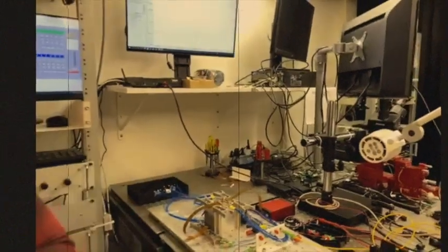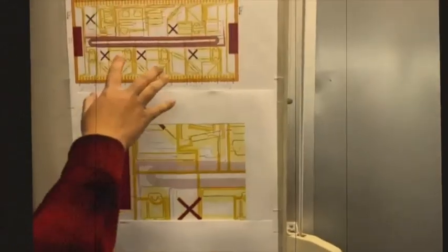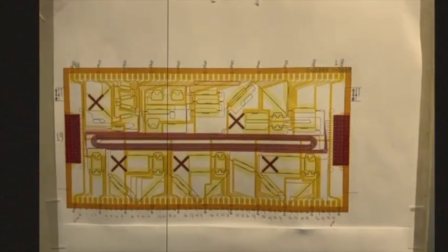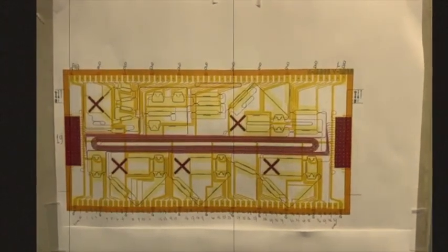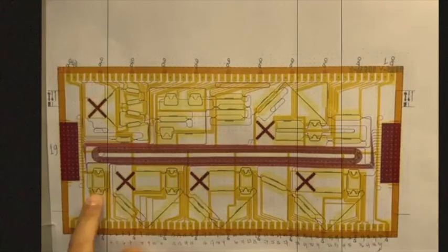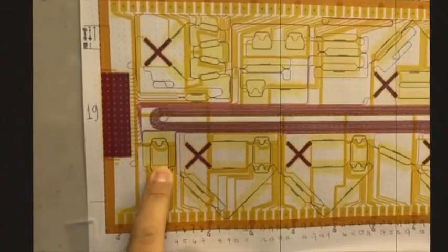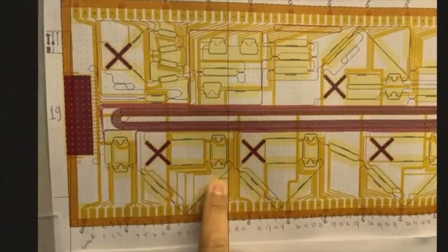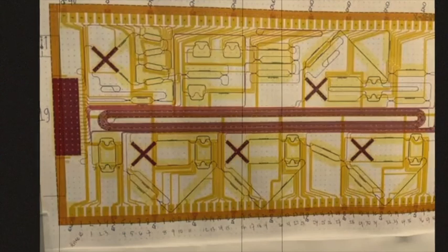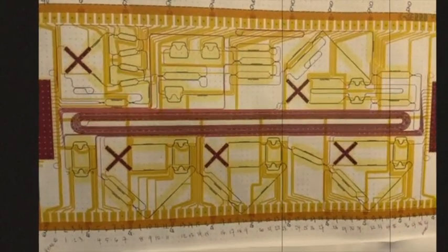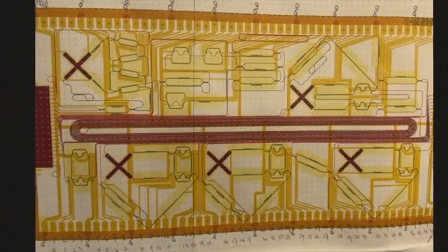What is actually inside of this chip, you can see from this layout schematic. This is the typical layout for optical photonic integrated circuits, similar to what you see in integrated circuit layout design. Inside of this chip, we have multiple optical circuits like ring resonators that have 4 ports, 2 inputs, 2 outputs. We have another ring resonator that can be double injected, which we typically call a FLAME, short for finite linear amplitude modulation elements, which can show very fancy responses that we can utilize for RF applications.